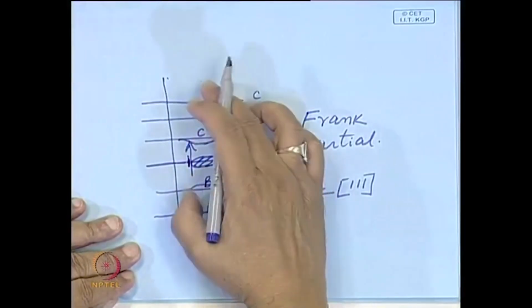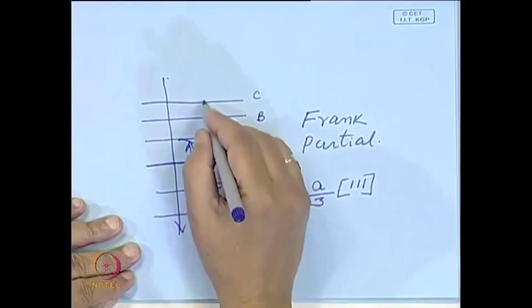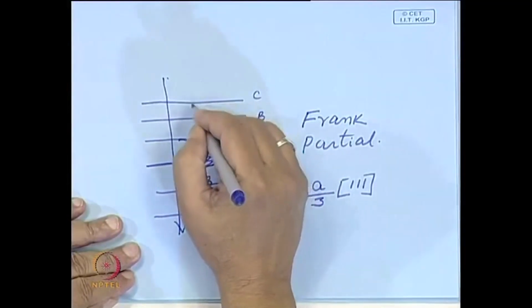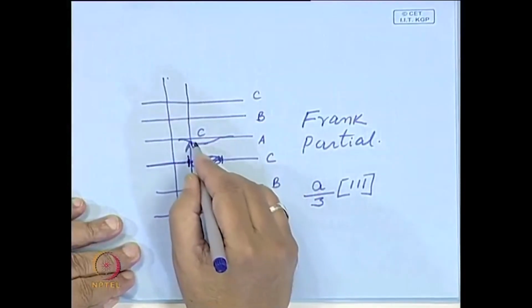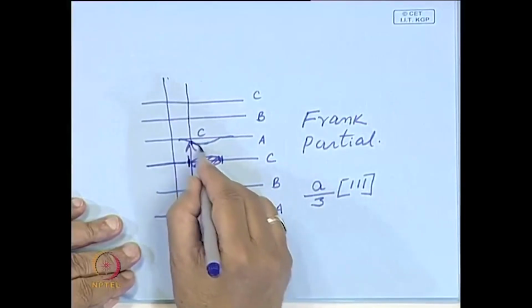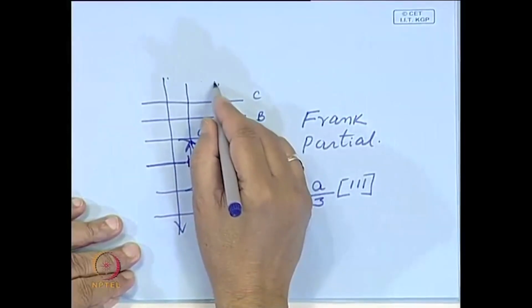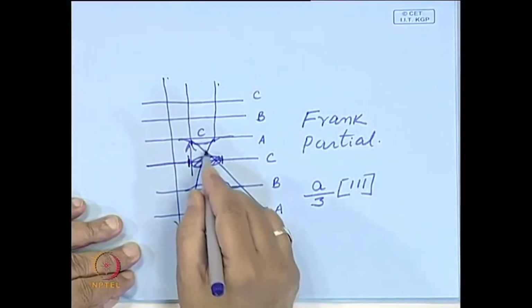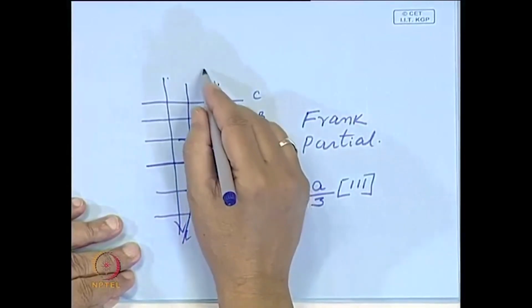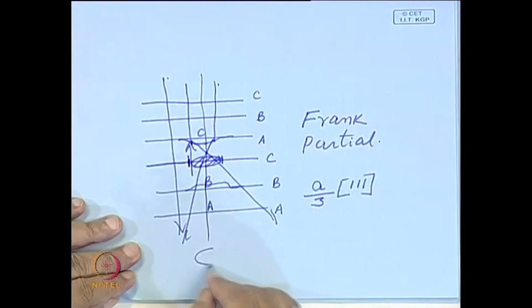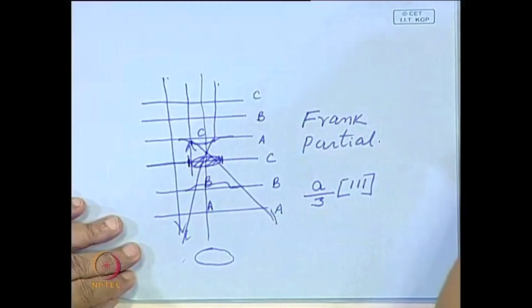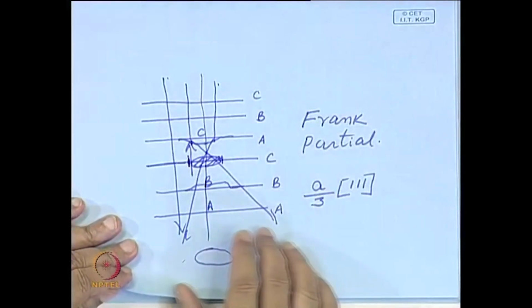And here you can clearly see that when the beam passes through this line, these planes are distorted and get diffracted out. So the beam which passes through this region will show a diffraction contrast, a ring like this, and by measuring the dimension of the ring, people have calculated the stacking fault energy also.